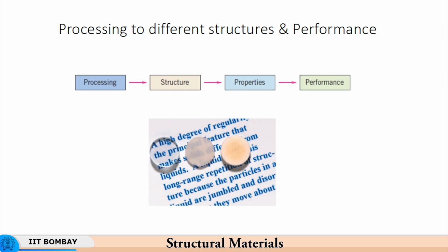Similarly, when you do welding, even of steels, what you need to take care of is that no oxygen should come in, because during arc welding particularly, you melt the material and that can get oxidized if there is an oxygen envelope around.